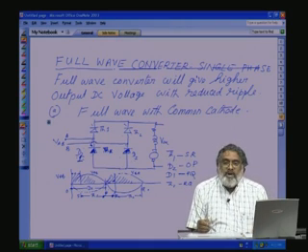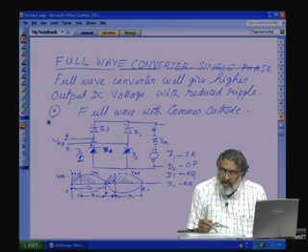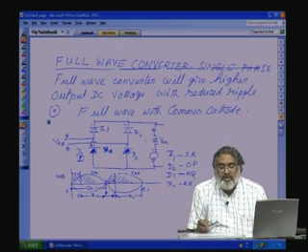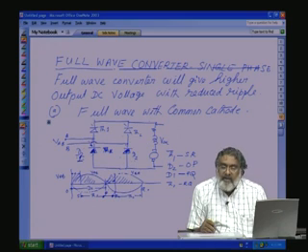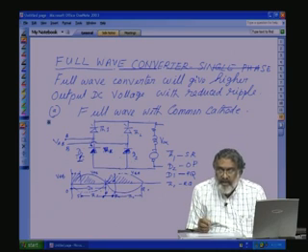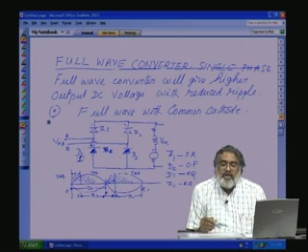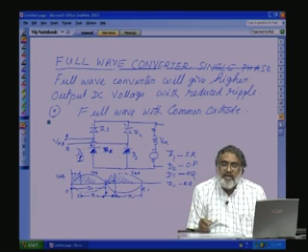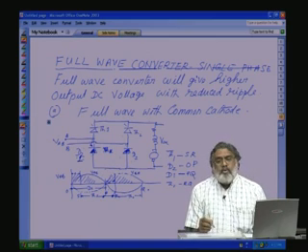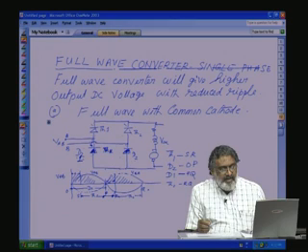So, with properly placing the diodes, what is the advantage? Full wave control is possible. At the same time, for inductive load, freewheeling action is also possible. That is the freewheeling action when the diode conducts and TH1 conducts. During the freewheeling period, the voltage across the load is 0, and the output ripple appears, that is, the input voltage waveform appears across the output only when the firing angle alpha is initiated for both the thyristors. This is the advantage.